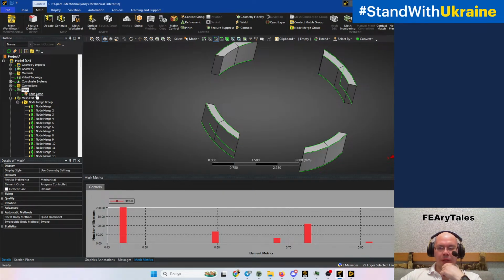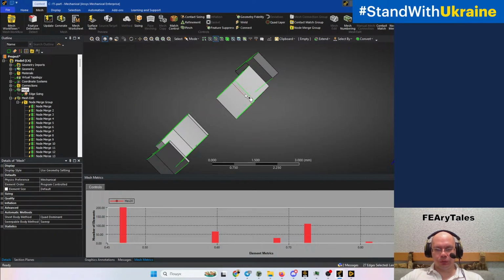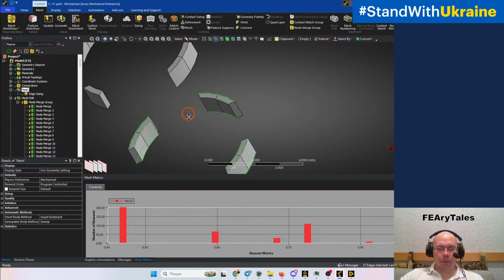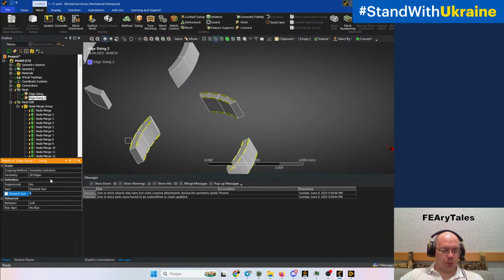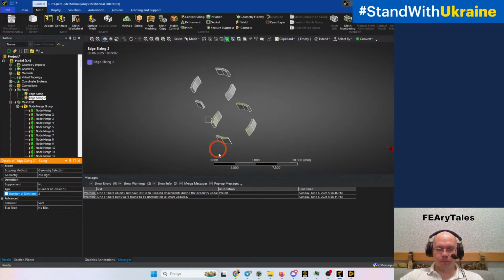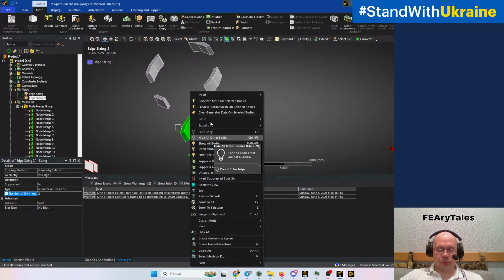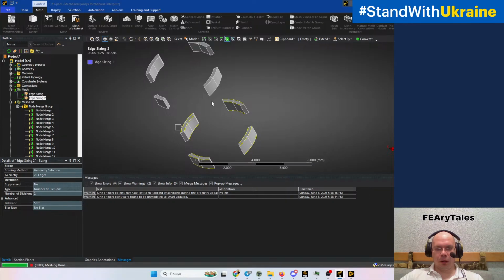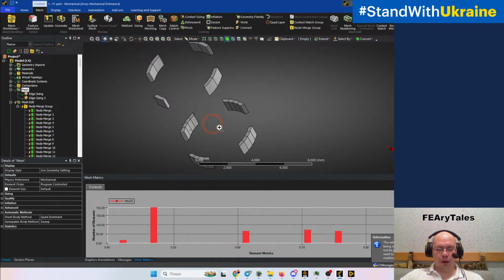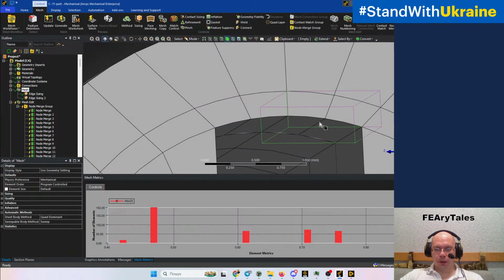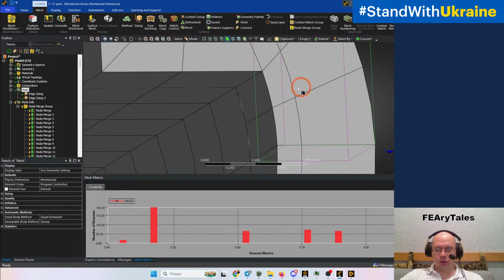We must exclude it from this edge sizing, but we need to add edge sizing with 2 number of divisions, and then when we create those type of mesh, yep, for this object the nodes will now correspond each other.